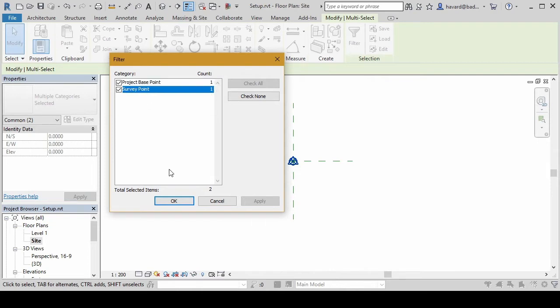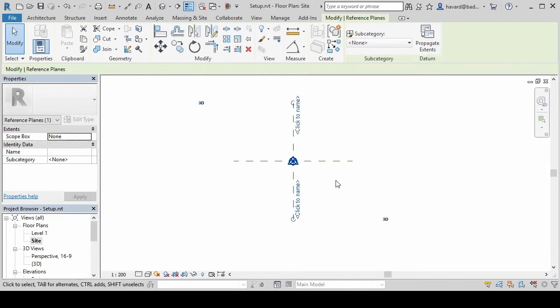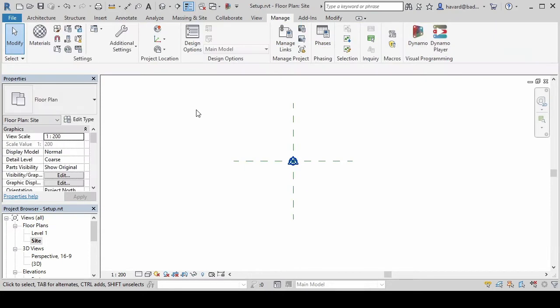These guys we're just going to keep in the local original Revit origin. So Revit has at least 3 origins. It has the local original origin that never moves. It's always going to be in the location of these reference planes unless someone moves the reference planes. By the way, mentioning that, maybe we should just go ahead and pin them.